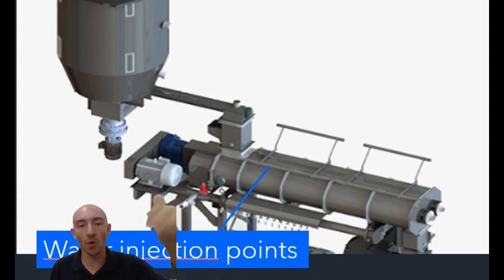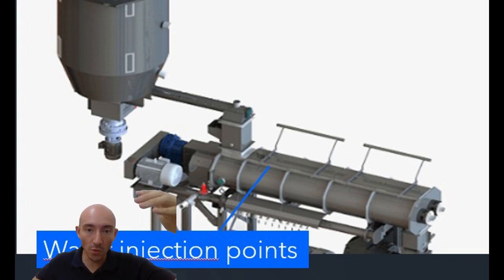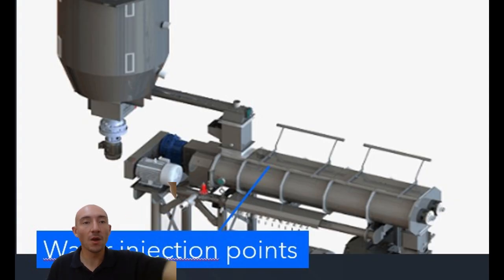Water should always go from the top of the conditioner. And why is that? Simple as gravity. Gravity will make water fall from the top to the bottom, which means that if we add water from the bottom, water will stay there. And we want the opposite. We want the paddles to push the mash up while we inject water from the top, right?